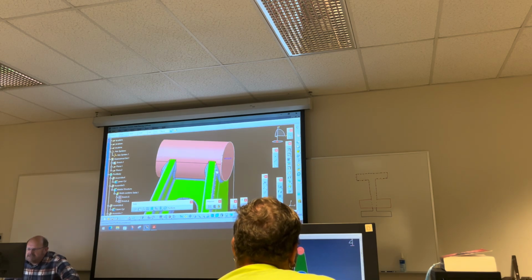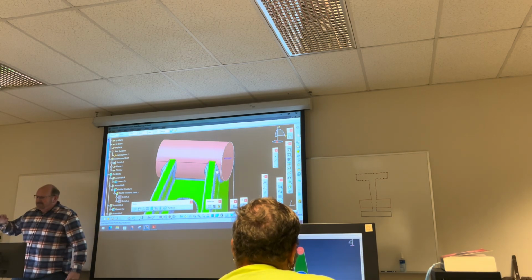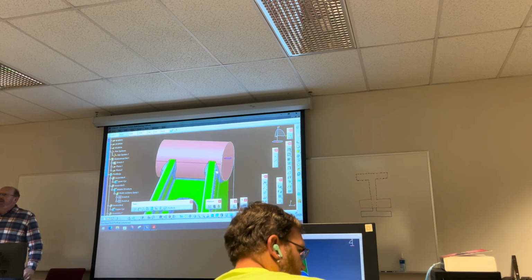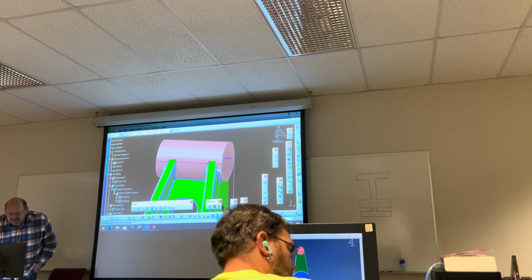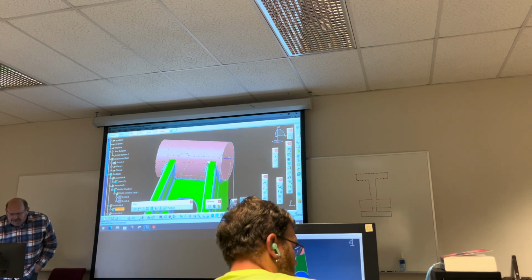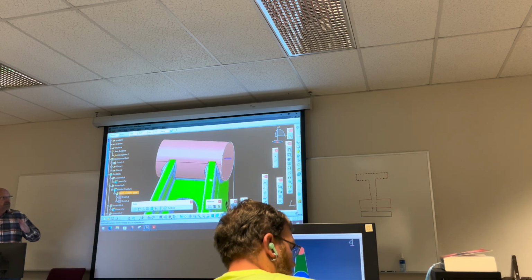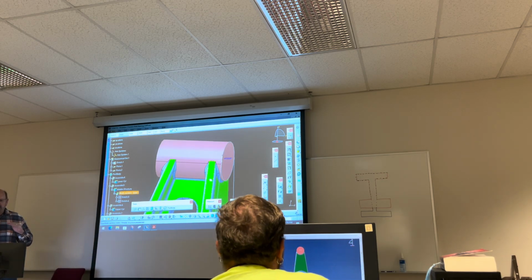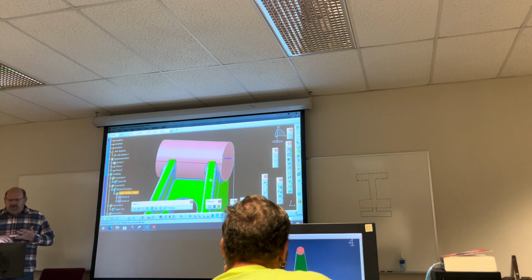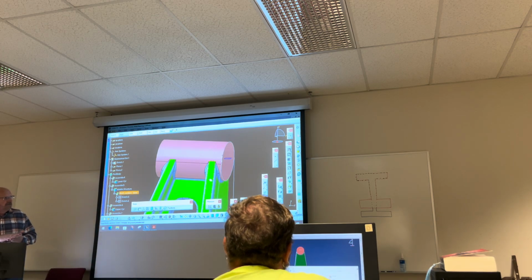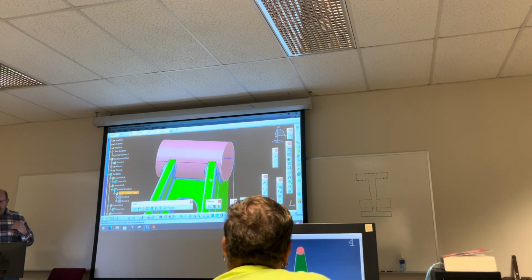So you'll see some of these parts where the fillet comes up and just curls over the top here and goes all the way back to the back. It's not very big because you're coming in at an angle, but that tells you that the sketch on the upper, or the lower, is not positioned and not coincident, or it's not where you've projected those lines into it.